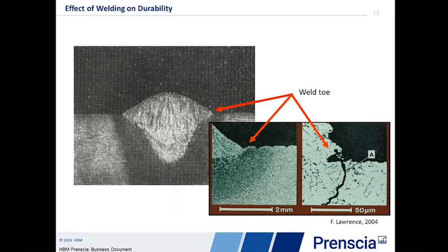In terms of geometry, if we start looking at things such as the weld toe here of this basically unimproved weld, you'll see not only is it very complex, but we're already looking at things such as crack initiators existing before we even start loading.